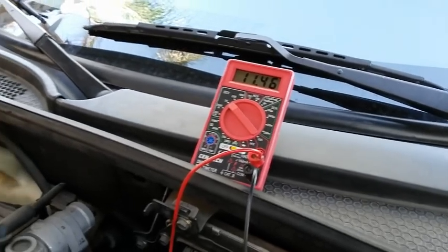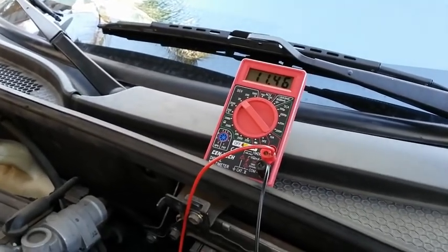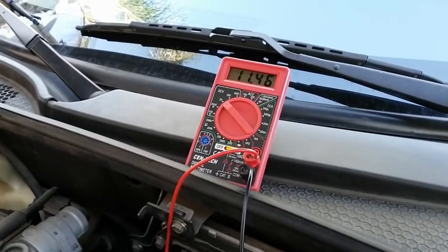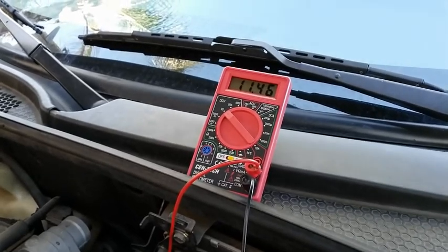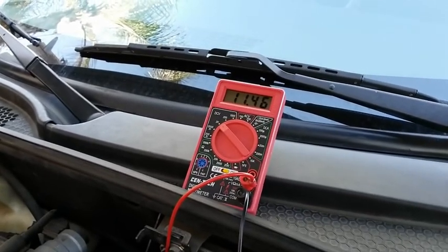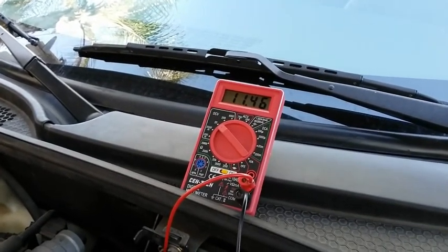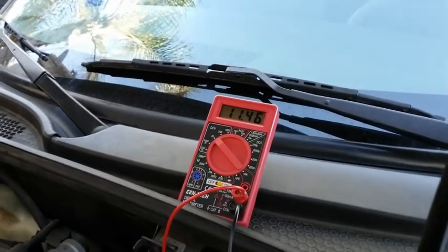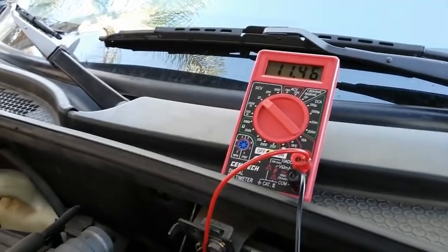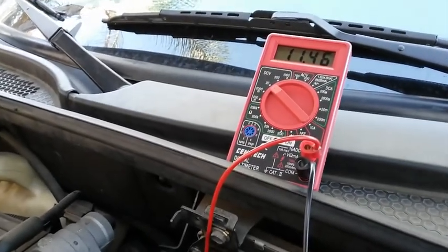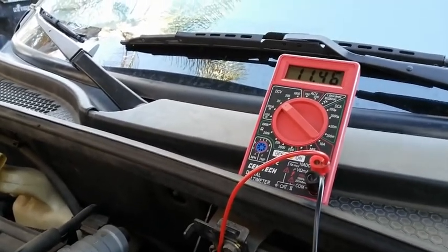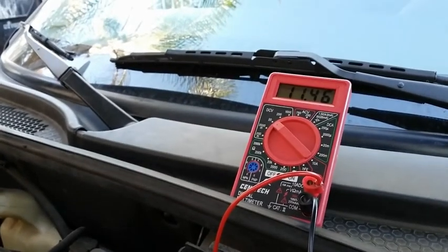But in this case, this oil pressure switch has an intermittent problem. During a cold startup, it may trigger an oil light, or during a long drive of 30 minutes or so, it may also trigger an engine oil light, but that's after a second key cycle. So I'm going to go ahead and replace this oil pressure switch, since the customer is requesting to get it replaced no matter what.